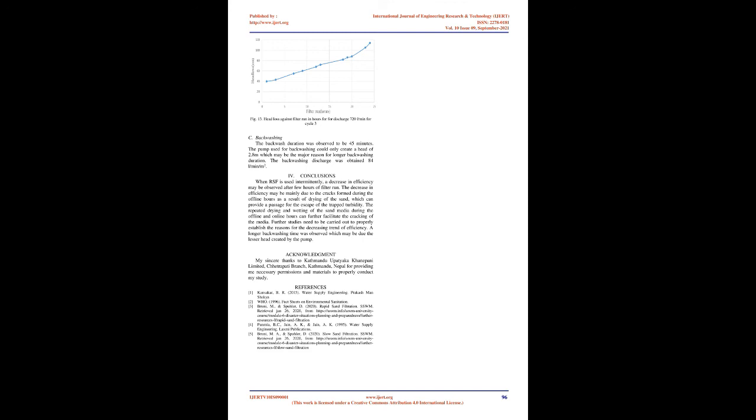Backwashing. The backwash duration was observed to be 45 minutes. The pump used for backwashing could only create a head of 2.8 m, which may be the major reason for the longer backwashing duration. The backwashing discharge was obtained as 84 L/min/m2.